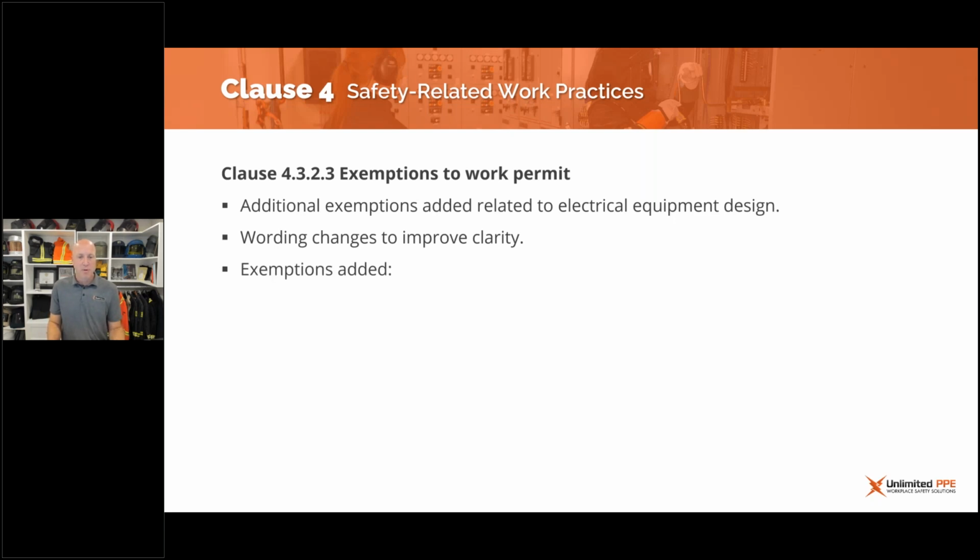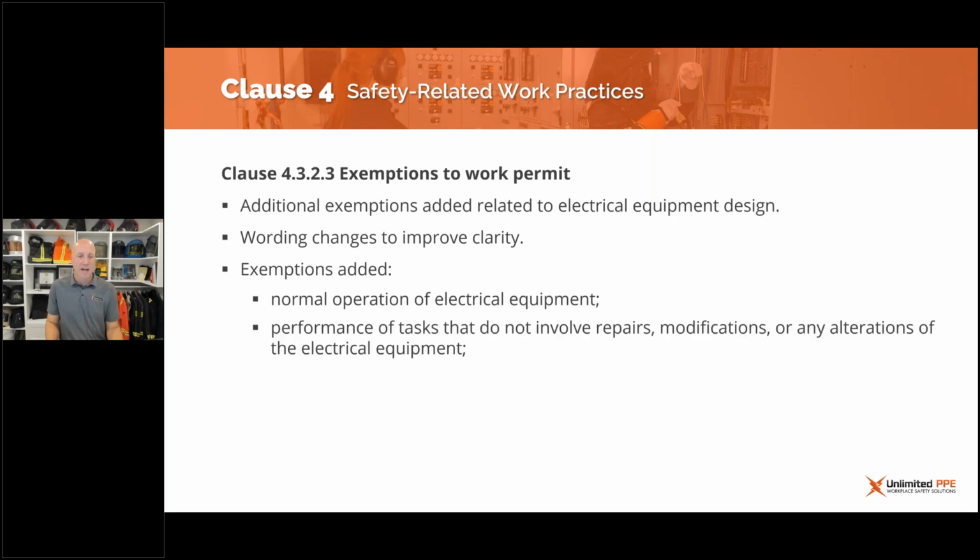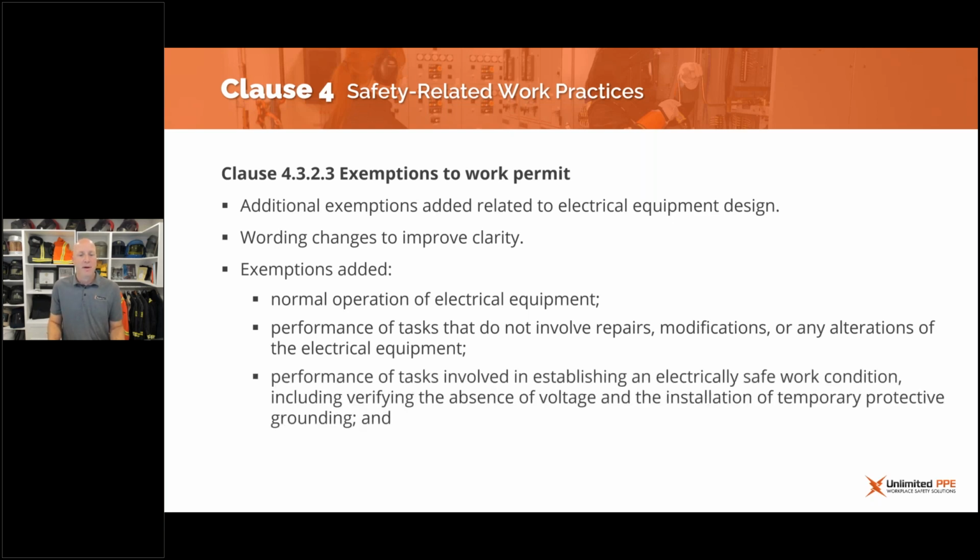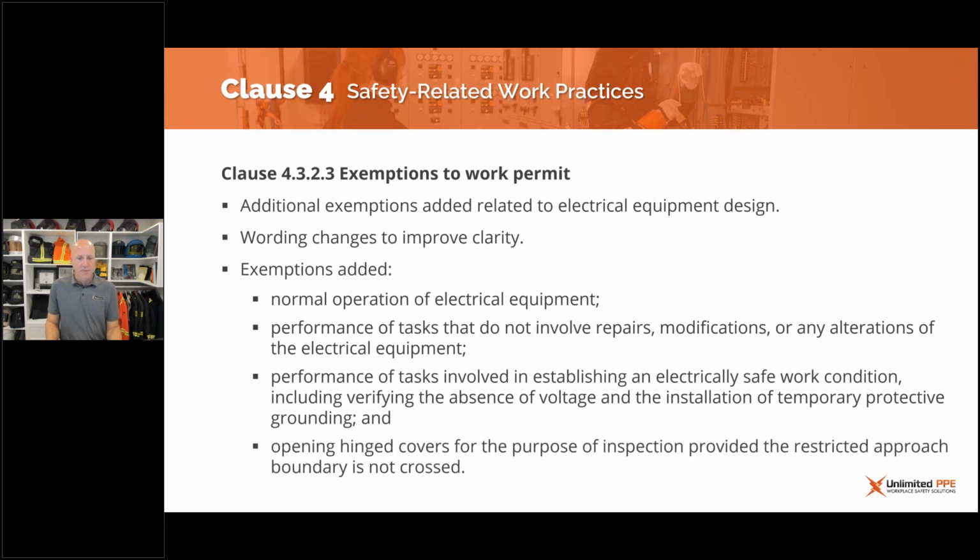Exemptions to a work permit: we've added exemptions to clarify when a work permit is required and when it's not. The exemptions that we've added relate to normal operation of electrical equipment, which would not require a work permit, performance of tasks that do not involve repairs, modifications, or any alterations of electrical equipment, and the verification of absence of voltage and installation of grounding.